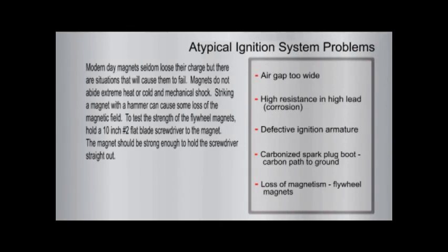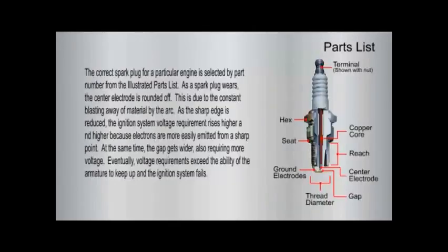To test the strength of the flywheel magnets, hold a 10-inch No. 2 flat blade screwdriver to the magnet. The magnet should be strong enough to hold the screwdriver straight out. The correct spark plug for a particular engine is selected by part number from the illustrated parts list.